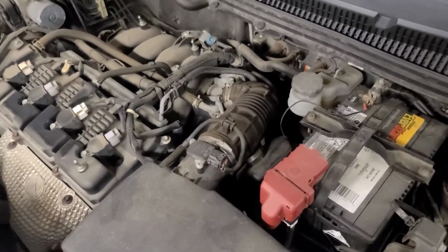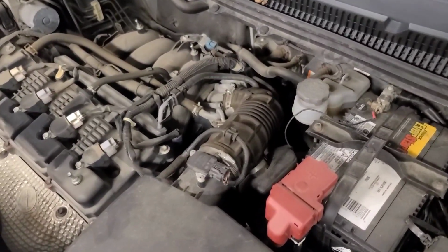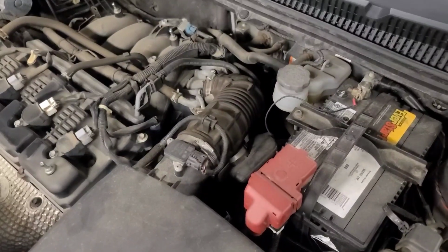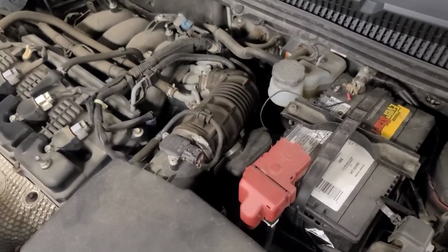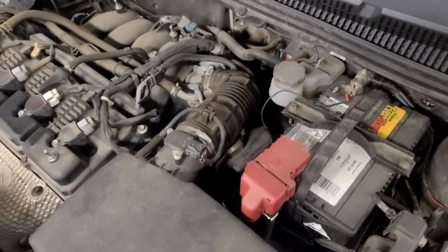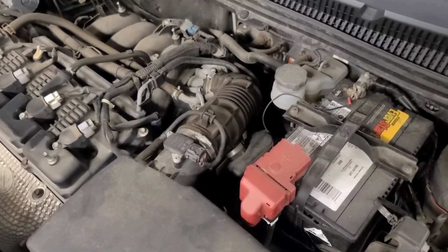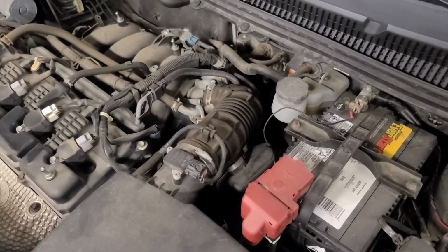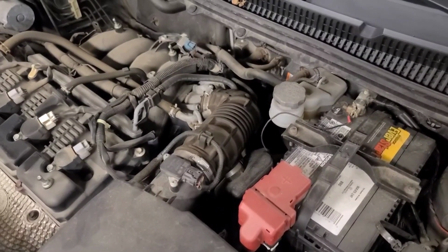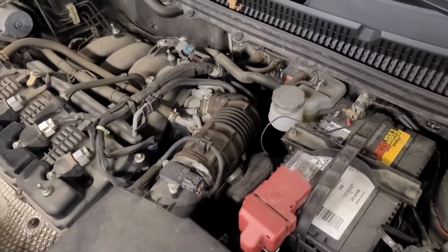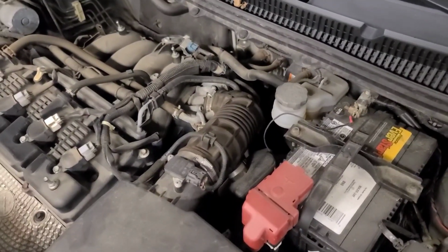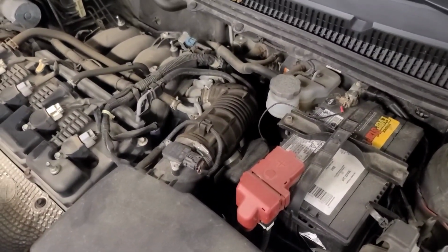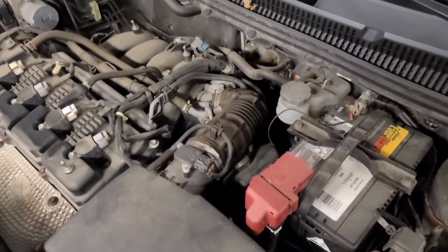Google search turned up the possibility that there could be carbon deposits in the throttle blades, throttle body. So I'm going to clean the throttle body, clean the mass airflow sensor. Yeah, that's about it. That's all we can do. The code apparently sets if the computer has to open the throttle blade more than it figures is necessary given the desired RPM and the actual RPM. So carbon deposits in the throttle bore would account for that. So we're going to do that, but other than clearing the code and giving it back to the customer and letting them drive it, it's inconclusive at best.